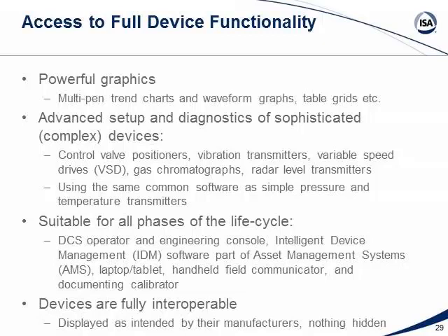Because in the end, if you want to do something powerful, like very advanced diagnostics, or maybe you have a guided wave radar and you want to draw the tank with some dots and a really complex UI, or maybe you have a little function block programming tool where you want to do some drag and drop, more than what you can do with DD, you need an app. You can do that with the FDI technology. The nice thing about that, again, is it's scalable from a development perspective. So the devices that don't need that functionality don't need to spend on it. It's going to keep the price of the devices down. But those devices that want that advanced functionality can provide that.